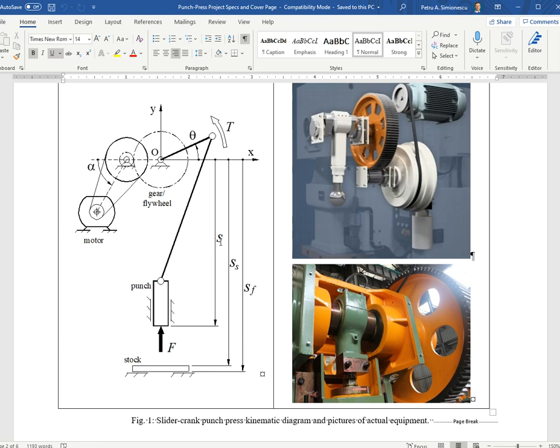You see here current displacement and start of punch, end of punch displacements. You can assume the punch length to be 0 in many of the calculations where you're doing the kinematic diagram and analyzing position, velocity, and acceleration of the punch in this configuration, that is punching downwards.